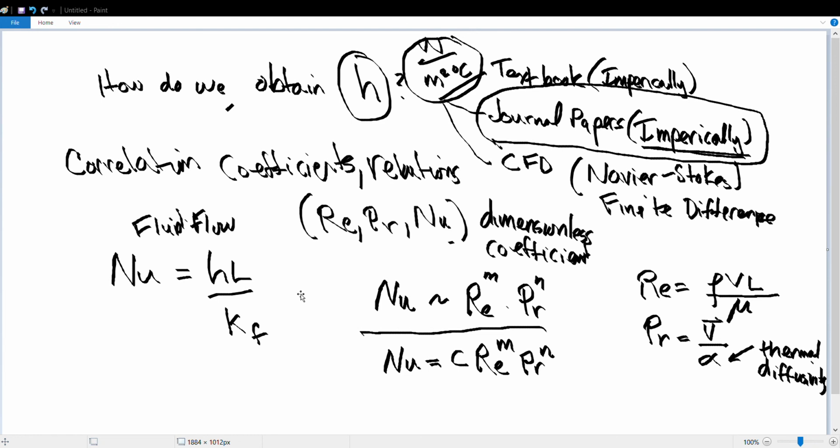This is very convoluted, but there are ways of calculating the Prandtl number so you can do these calculations. And again, the end result is to get that Nusselt number, which you could then use to get a heat transfer coefficient, depending on the geometry, the flow direction, and how these are spaced. That would be your L, the distance between these cylinders and things like that. And then I think that's all I wanted to show you with this.